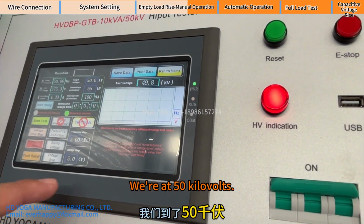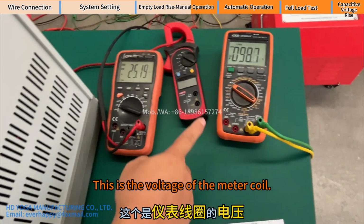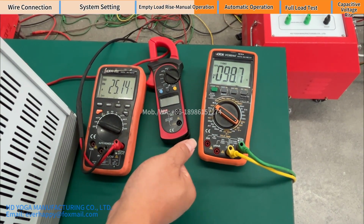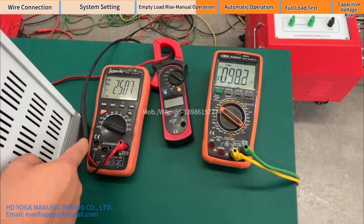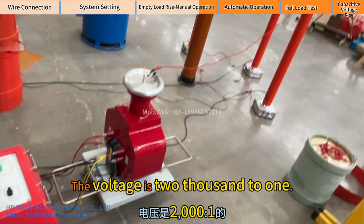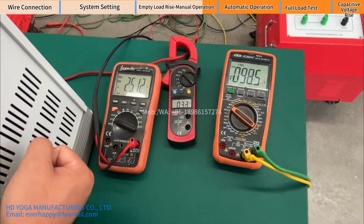We're at 50 kilovolts. This is 49.9. It's 50 kilovolts. This is the voltage of the meter coil. It's full voltage, which is 100 volts. Yes. This should be correct. This is the voltage sampled by the voltage divider. The ratio is 2000 to 1. So 25 by 2000 is 50 kilovolts.